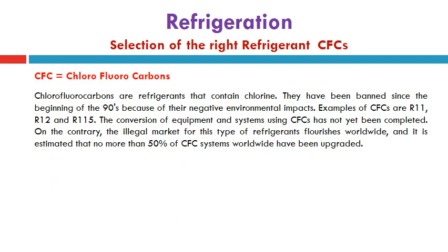CFC, chlorofluorocarbon. Chlorofluorocarbons are refrigerants that contain chlorine. They have been banned since the beginning of the 90s because of their negative environmental impacts. Examples of CFCs are R12, R11 and R115.